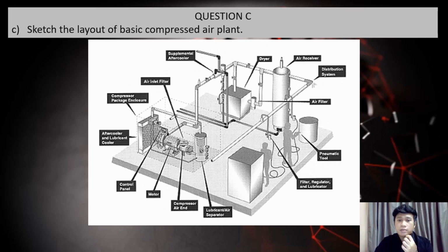Moisture drain traps are used for removal of moisture in the compressed air. These traps resemble steam traps. Various types of traps are used, such as manual drain cocks, time-based automatic drain valves, and so on. Air receivers are provided as storage, smoothing the processing air output, and reducing pressure variations from the compressor.